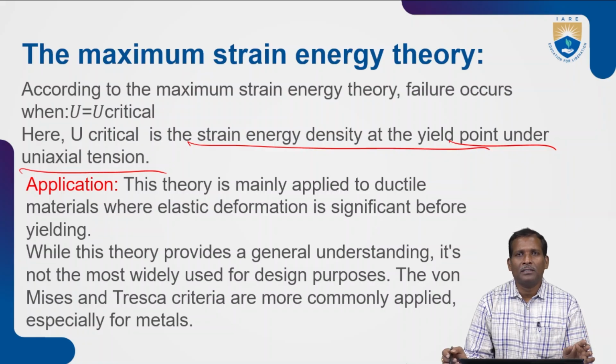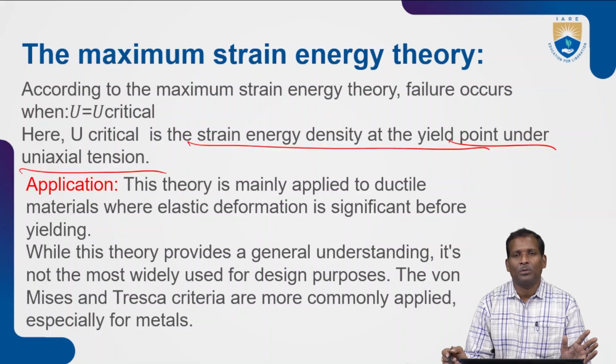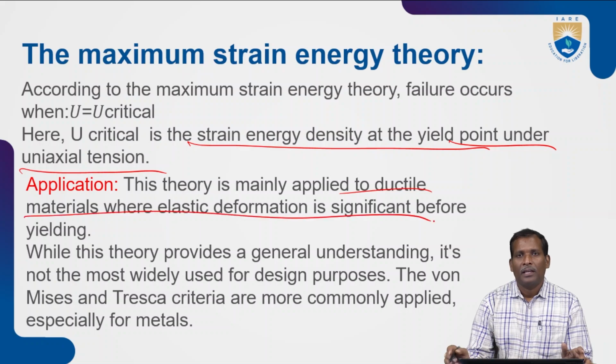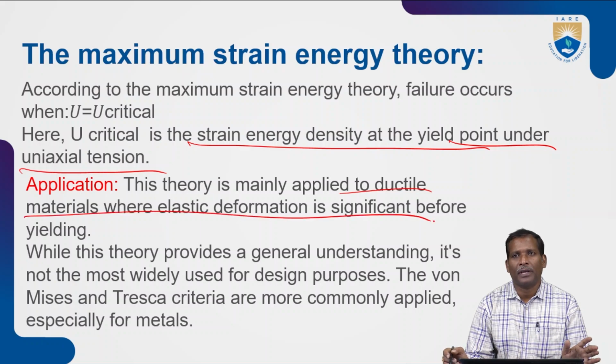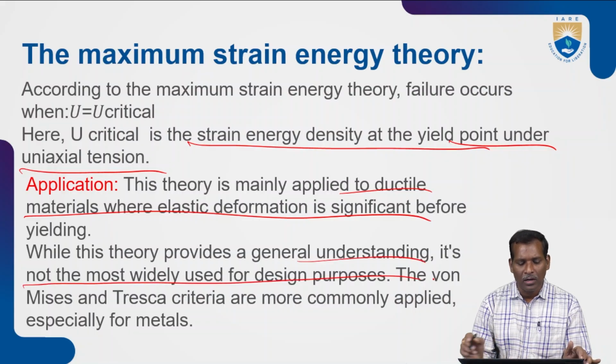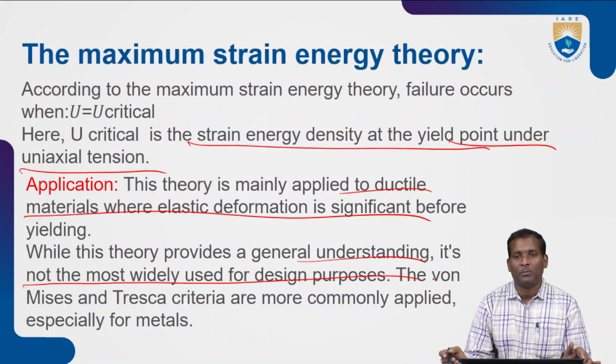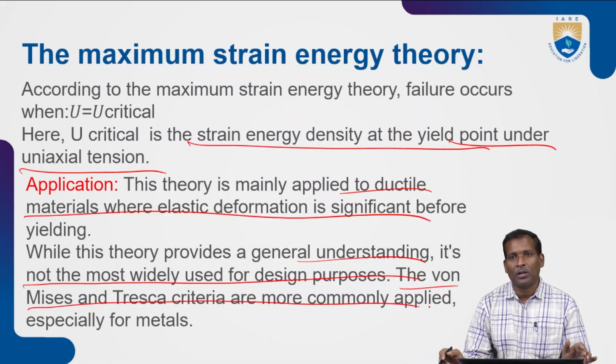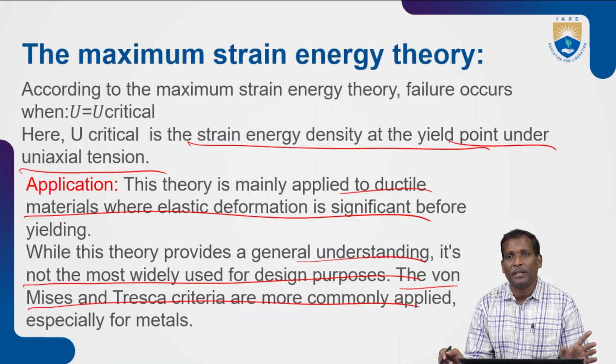So what are the applications of this strain energy theory? This theory is mainly applied to ductile materials, where the elastic deformation is significant before yielding. While this theory provides a general understanding, it is not the most widely used for design purposes. The von Mises and Tresca criteria are more commonly applied, especially for metals.